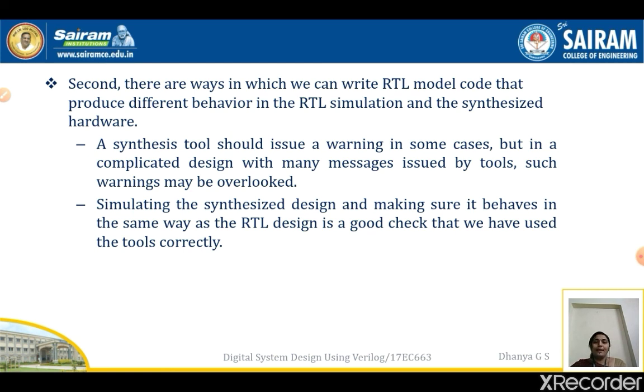Second, there are ways in which we can write RTL model code that produce different behavior in the RTL simulation and the synthesized hardware. A synthesis tool should issue a warning in some cases. In some cases it will issue a warning that something is not proper. But if you are going for a complicated design, it is not necessary to take care of all those things, so small issues they will neglect. Simulating the synthesized design and making sure it behaves the same way as the RTL design is a good check that we have used